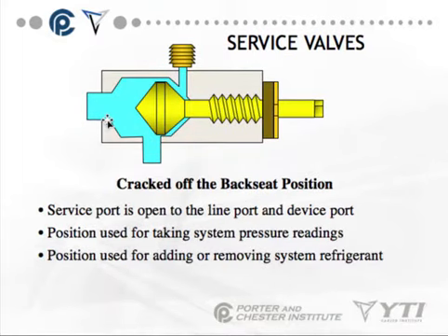Cracked off the back seat position, or we call it mid-seated. The service port is open, the line port is open, and the device port is open. It's the position used for taking system pressure readings. It's also the position used for adding or removing system refrigerant: mid-seated.